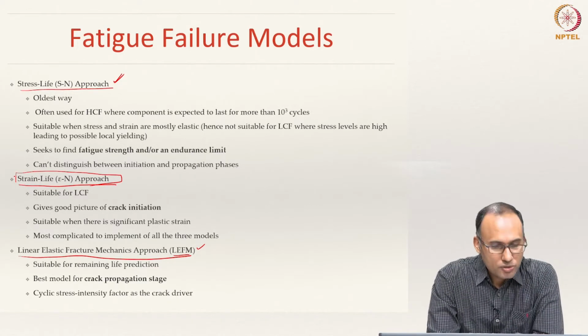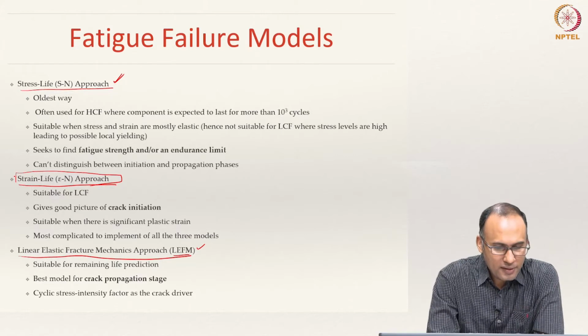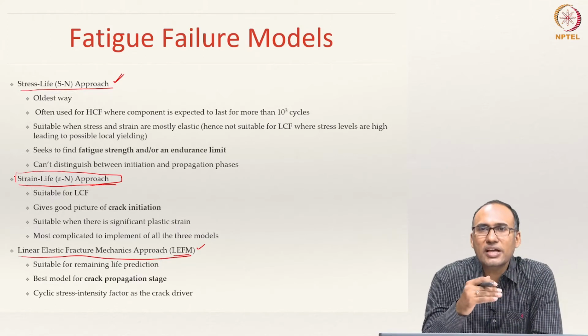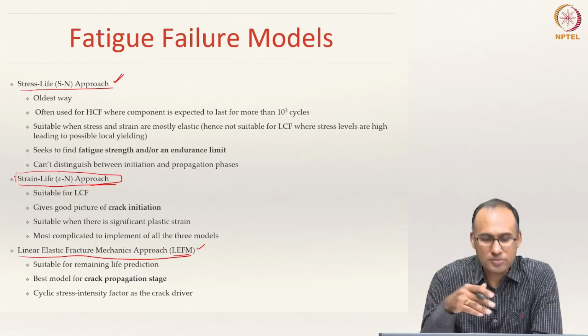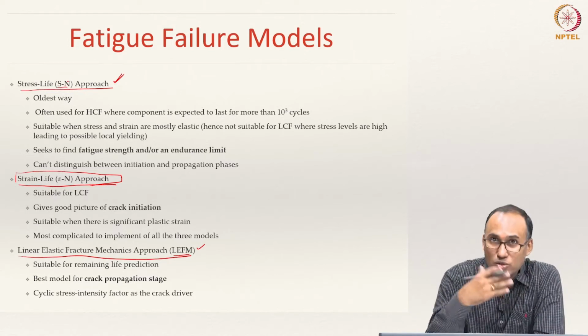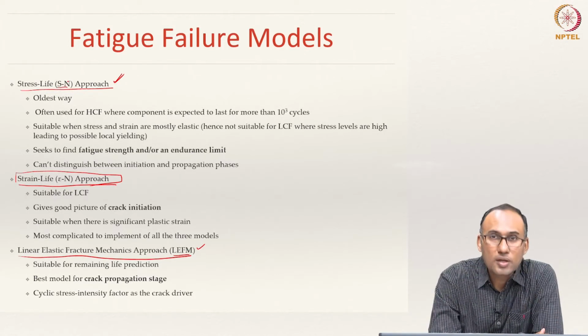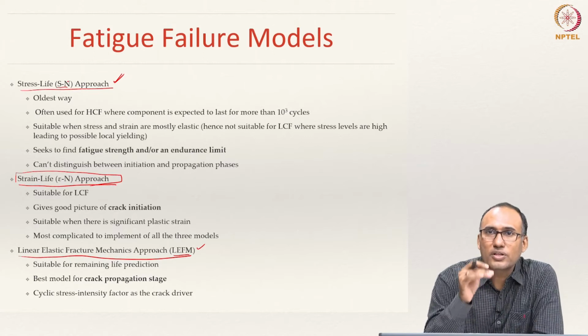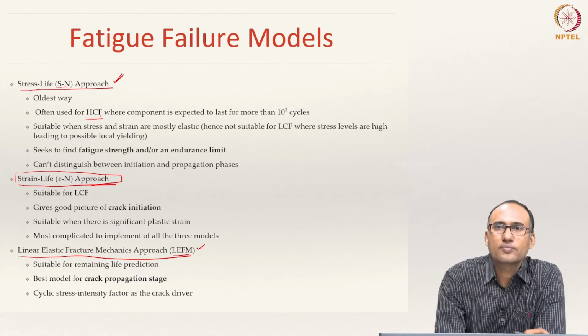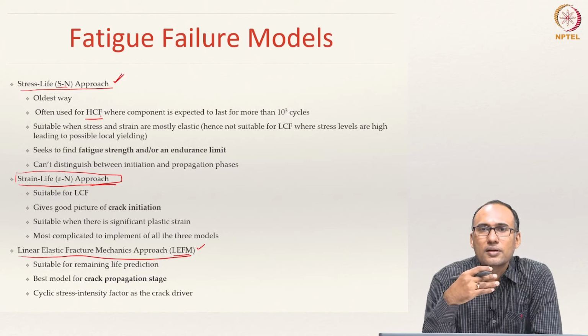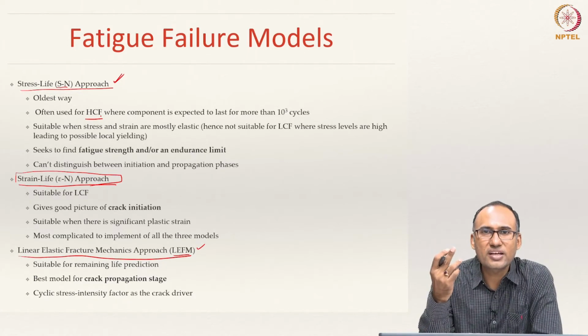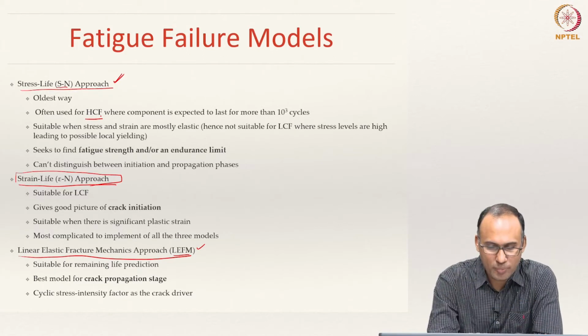Okay. So what do we mean by the stress life approach? The stress life approach is actually the oldest approach, because the SN diagram is from the stress life approach, and this is often used for high cycle fatigue. That means if your component is to last beyond 1000 cycles, that is when you use the stress life approach.